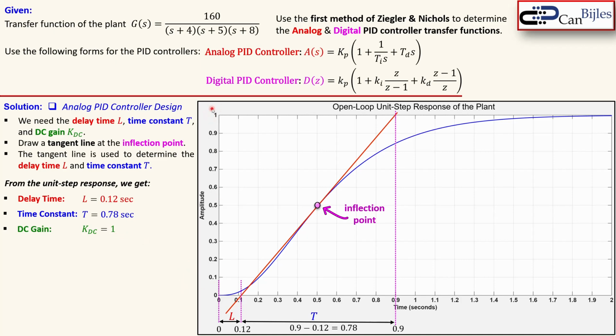If, for example, KDC was 7, that would show because you start with a unit step input. So if you do not have the transfer function, and you apply your unit step input on an unknown black box and you get this response, then your plant transfer function will be given by this, where you see the lag, which is our time delay, and our first order system approximation in cascade form, where you also see the 3 parameters which are determined.